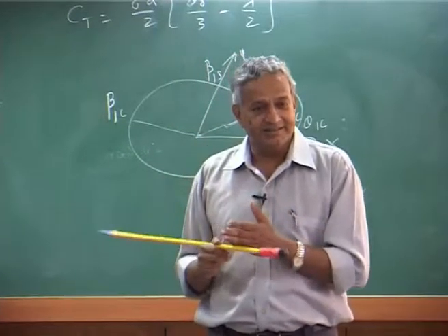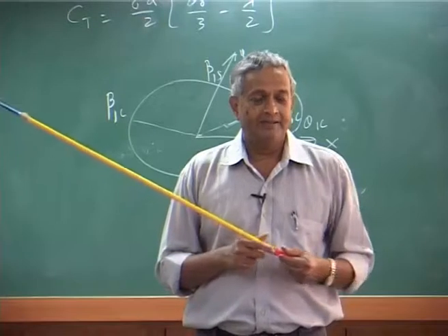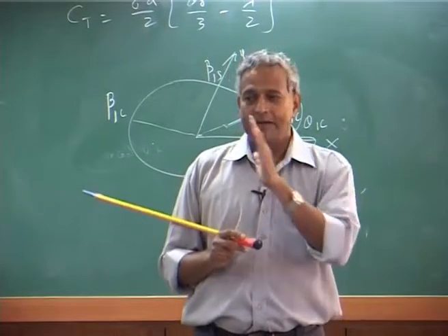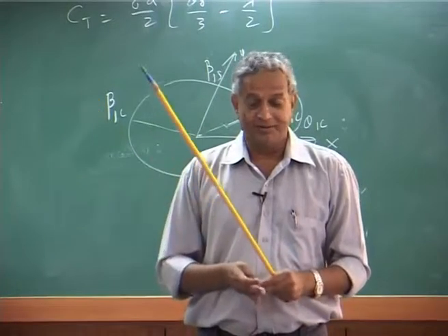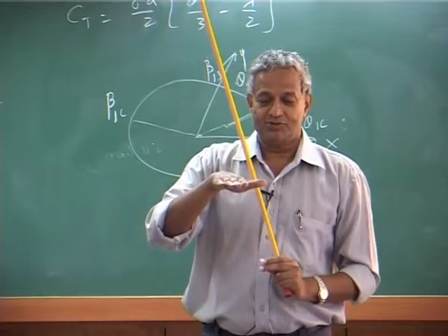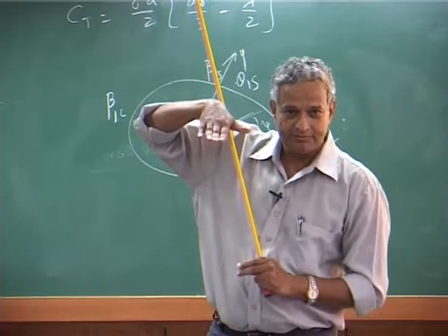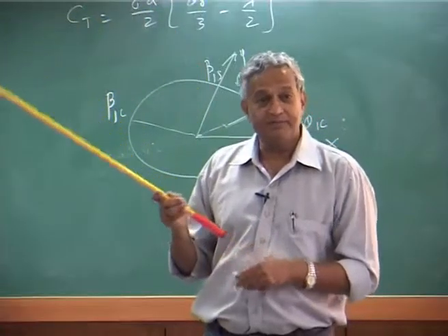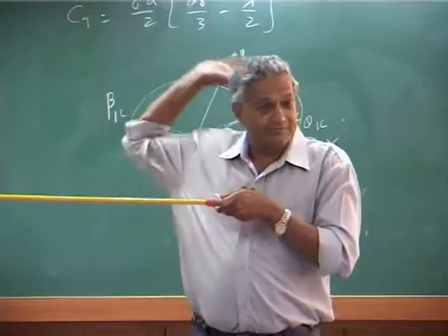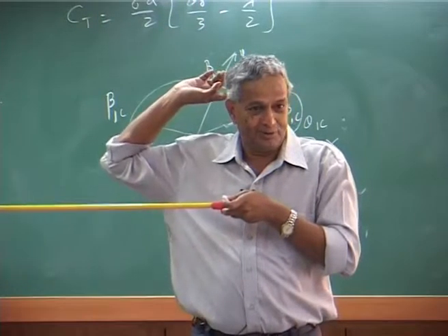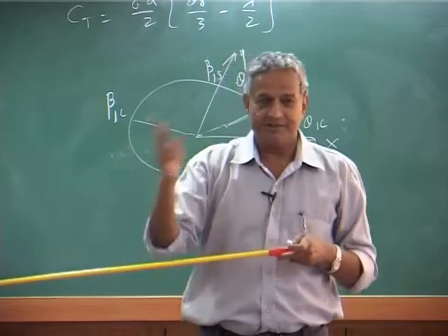How it changes, that is what we will derive, the phase shift between input and output. Now, if the rotor disc is to tilt forward down, you must change the pitch angle when the blade is here, not at the 0. This is the key, important. There is a phase shift of 90.